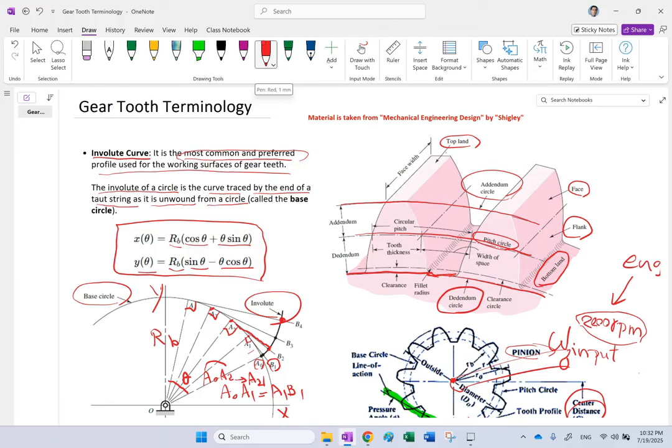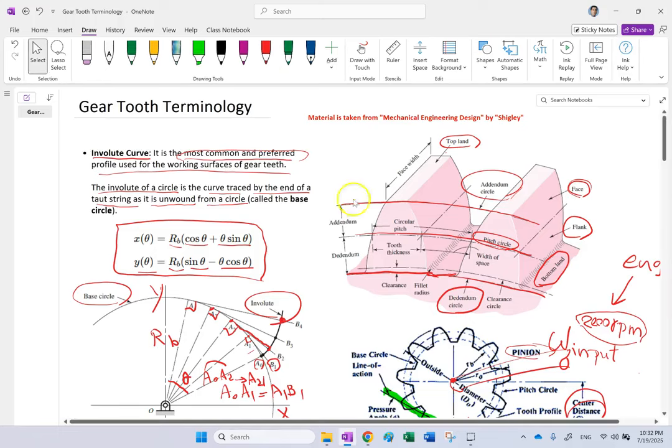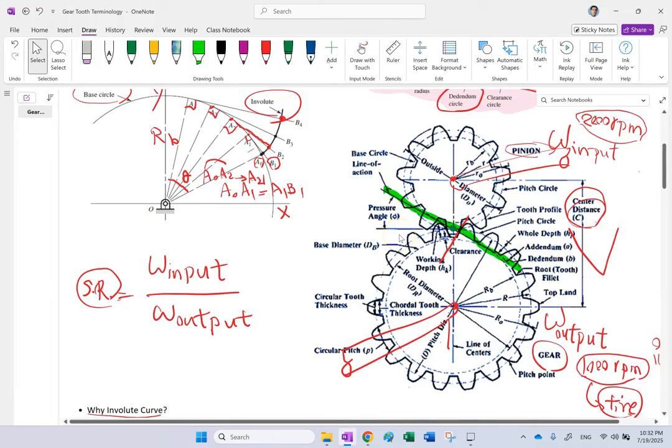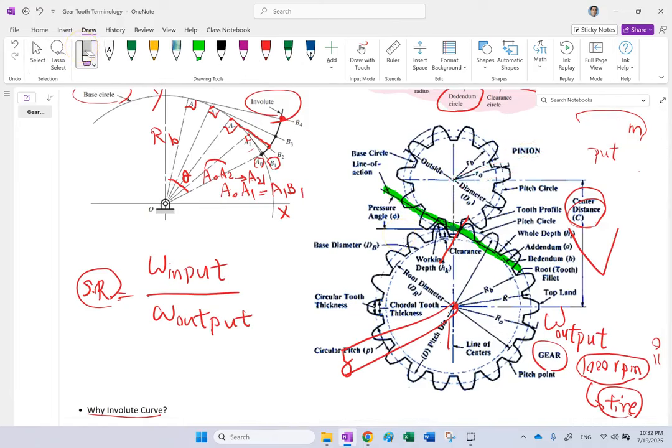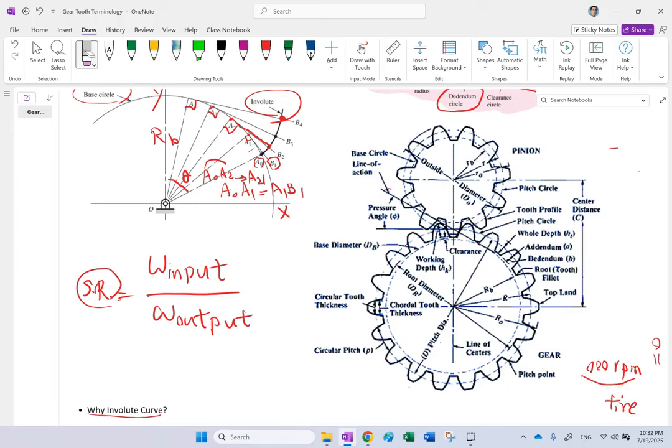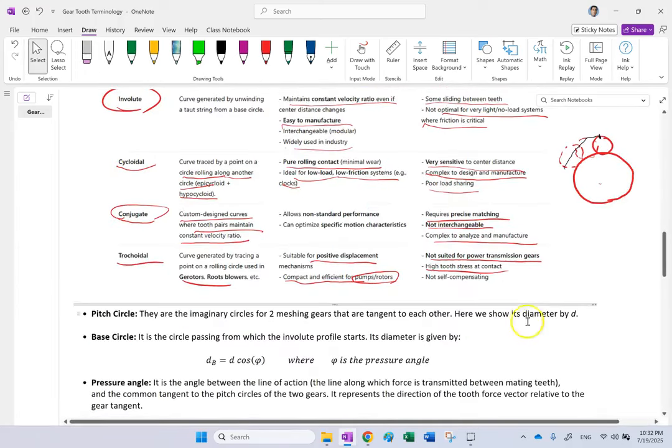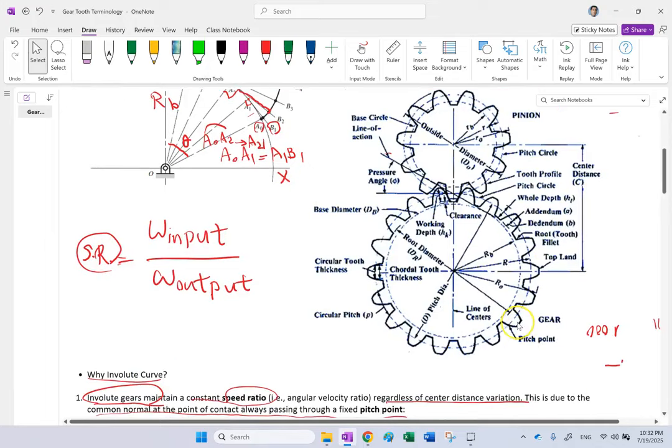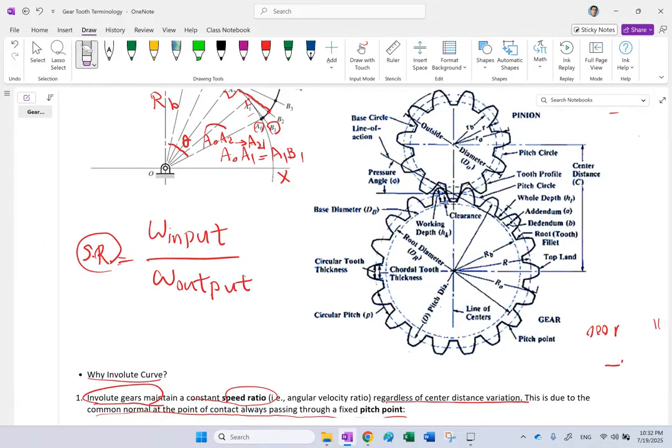The part on the side of the involute curve that is above the pitch, you might call the face. The one below it, you might call the flank. So let's talk a little bit about this pitch circle. What is this imaginary circle? Why is it very important? The reason is this. If you look at 2 gears that are meshed together and working together, and you show the addendum, dedendum, and the pitch circles of both of these gears, what would you see?